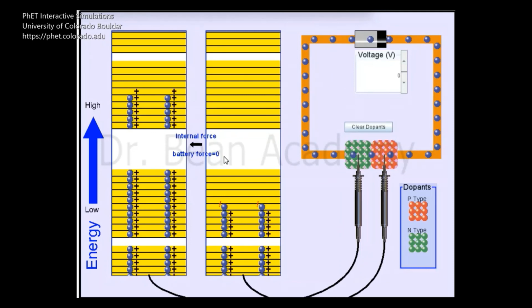But the pattern of diffusion is like that. When they diffuse, they ultimately build up an electric field across the boundary of the two materials where they are combined, and as a result the further diffusion will stop and an electric barrier will be formed. So we saw that silicon has a potential barrier of around 0.6 volts. Now the p-n junction has been formed, and the n-type material is here and the p-type material is there.